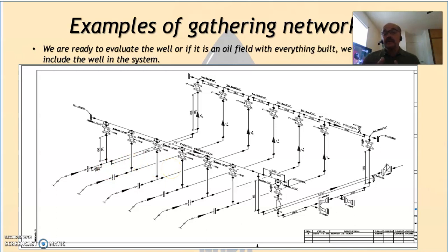where we put 5 wells. We have a testing manifold right here. We can go across a Coriolis if it's the system that can work, and then we have the general manifold. So if we test the well and the well has 100 pounds in THP, and when we put it with the rest of the wells, it keeps the 100 pounds, the well is producing the same when it's being tested and when it's with the other guys.